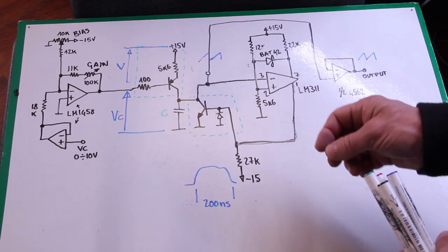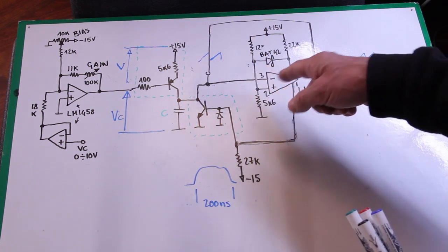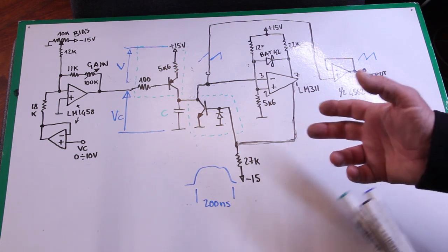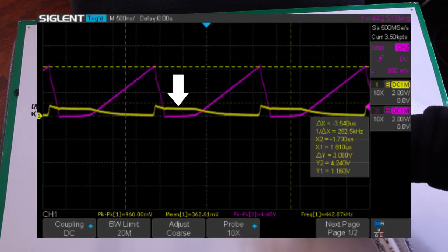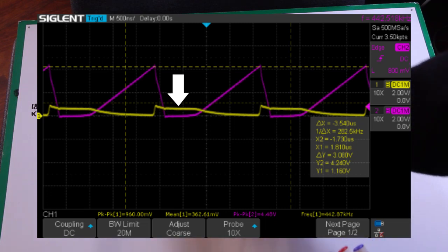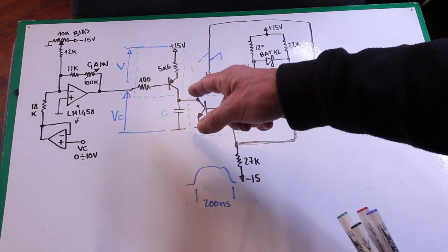However, notice that the problem is with the smaller capacitance, because as the voltage falls below the comparator's threshold, while its output switches with a small delay, the transistor still has some charges stored in its base-emitter junction, despite the negative voltage applied that should help in draining them out.